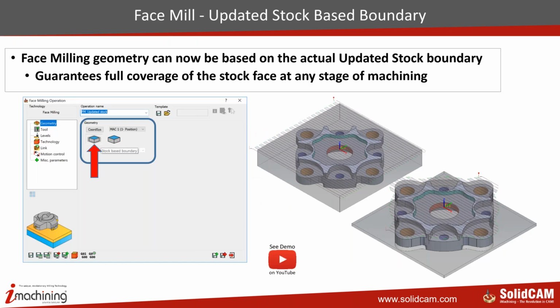Another new function is the updated stock based boundary inside the face milling operation. Now when you go to face milling, you have two options: one is the stock based boundary, another one is the target boundary. By default, it is always set to stock based boundary. Depending on the stock condition, the boundary will be updated automatically.